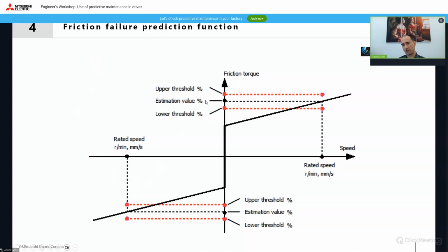And this time generally is at least 90 hours of operation, and at least once it should operate for 3 hours or longer without stopping or turning off the machine, because it also takes into consideration the impact of the temperature of the axis on the estimation of the torque and so on. So quite a lot of factors are collected together to find out these proper levels.